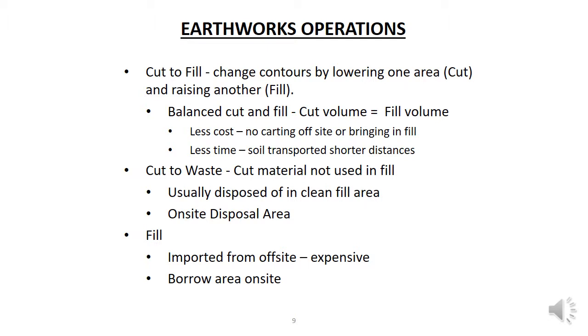Earthworks for a road typically consists of cut and fills. That is areas where the soil is excavated, that is cut areas, and areas where soil is placed, that is fill areas. There may be a mix of the different types of earthworks along the length of a road project, with cuttings in one area, sideling cuts and fills in another, and fill embankments in another. Managing the cut and fill soil volumes is an important part of designing and planning an earthworks project.